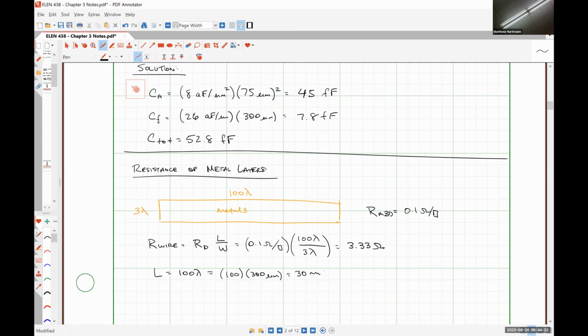And it's very, very easy to cause what's called ground bounce and things like that, where effectively you're having a significant enough voltage drop over your section of wire connecting 2 points in a circuit to cause, say, your transistor to not actually be able to turn on.